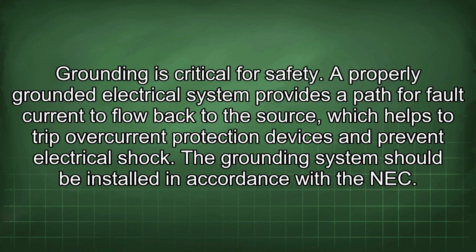Grounding is critical for safety. A properly grounded electrical system provides a path for fault current to flow back to the source, which helps to trip overcurrent protection devices and prevent electrical shock. The grounding system should be installed in accordance with the NEC.